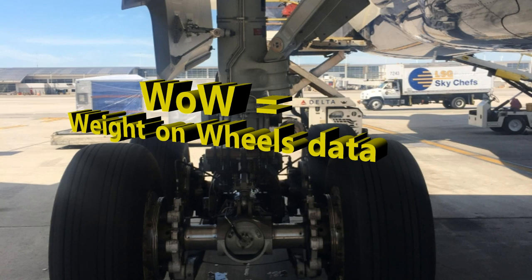What it's going to be doing is sending weight on wheels data to the other systems on board the aircraft to show that the aircraft is either on the ground or in flight. And it's going to be calculating if the weight is on wheels for each gear, if it's balanced, essentially. But there's a logic that's going on. This is all done by the Common Remote Data Concentrator that's doing an AND logic of the output from those two sensors.